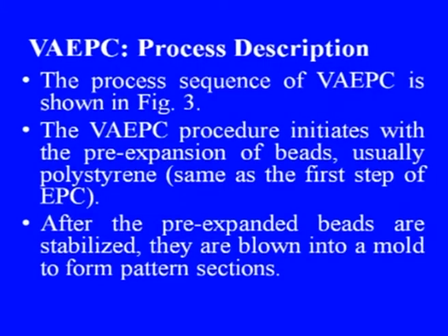The procedure initiates with the pre-expansion of the beads, usually polystyrene. This is the same as the first step of the earlier discussed evaporative pattern casting process.